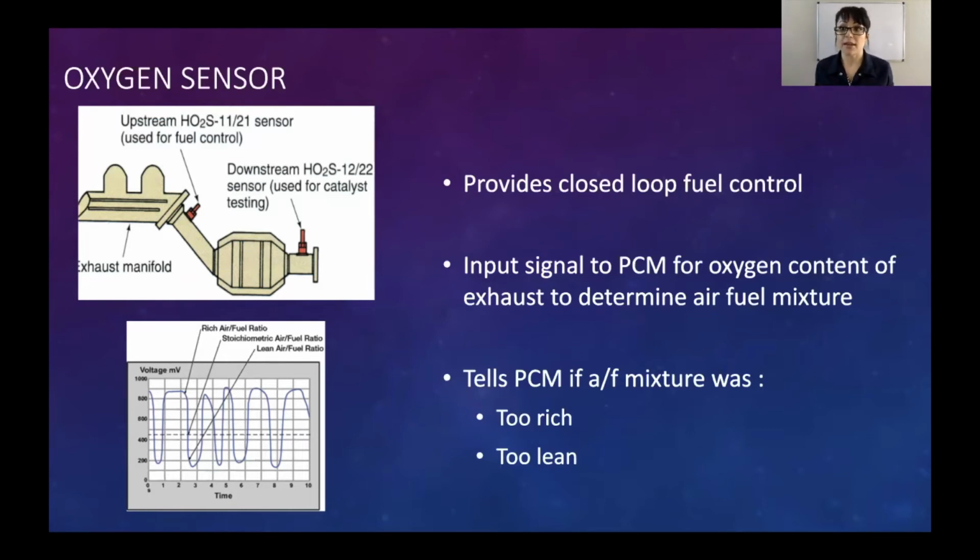Or what if the heating circuit is bad on the O2 sensor? So it's not the sensor itself, but it's the heating wiring, which is usually not the case. If you get a heater code, it's generally a bad heater in the O2, but there's ways to test that. So you never want to see a code and be like, oh, it says oxygen sensor, I need to replace the oxygen sensor. That's not necessarily what you want to do, because it doesn't mean that it's bad. It's just saying, hey, this reading's wonky, you should probably take a look at this.